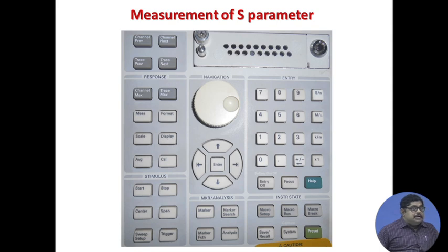Averaging means, suppose when you do any measurement in the presence of noise, now if you repeat that measurement, same quantity you measure several times and take the average of that, your SNR will improve. Averaging improves SNR. Why? Because the signal is a deterministic thing. So, if you repeat the same measurement several times, suppose some signal value is 5 volt, I am taking 5 volt several times.